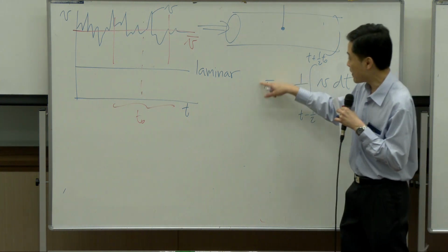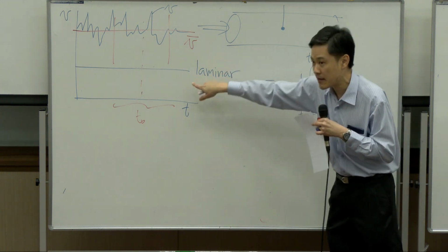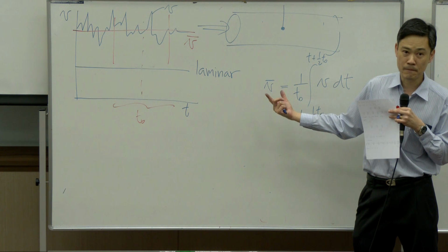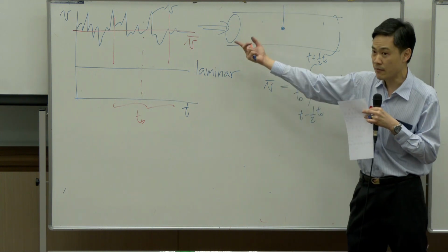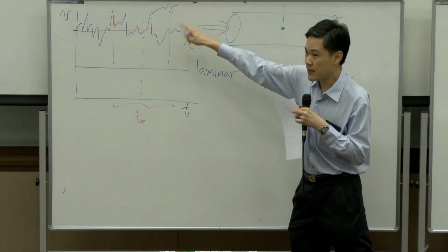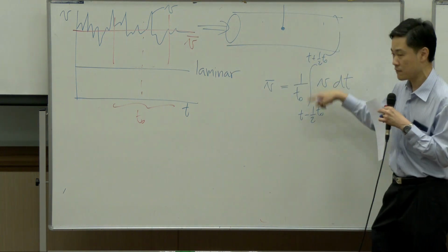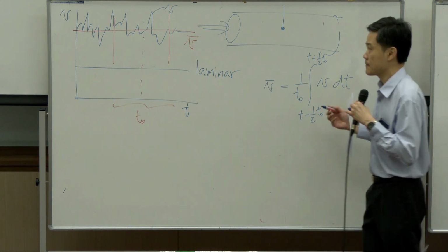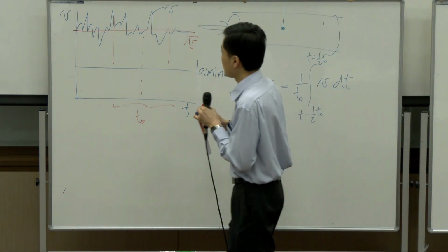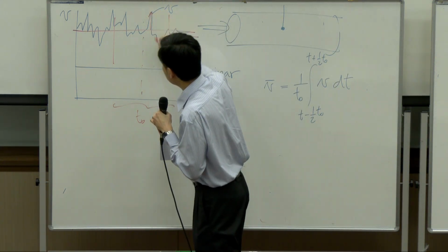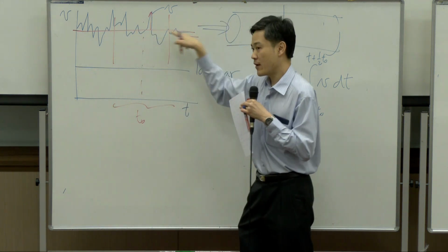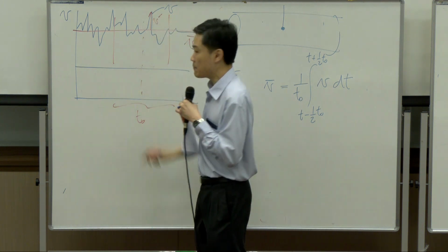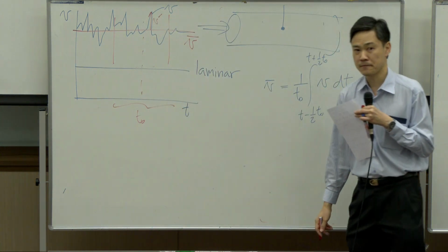Of course, if you apply time average velocity to laminar flow, you end up with a single constant number. If it is turbulent flow, however, the function is random, so this number would be very difficult to find. Now, the deviation from the average value to the actual value represents the fluctuation itself.